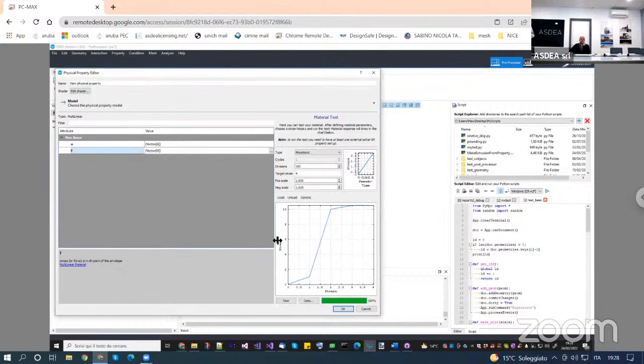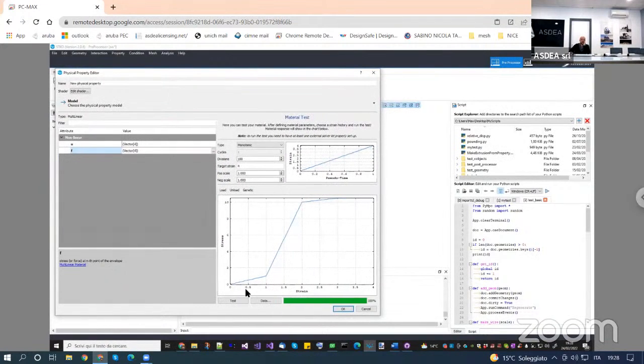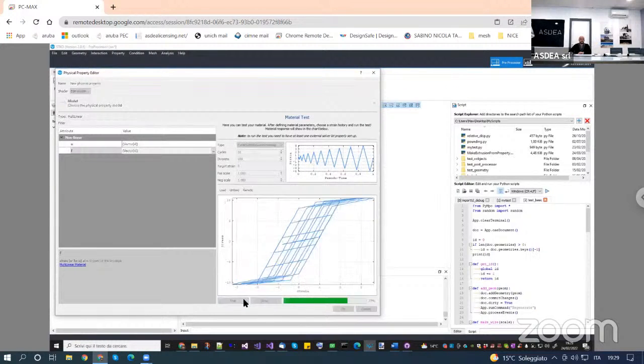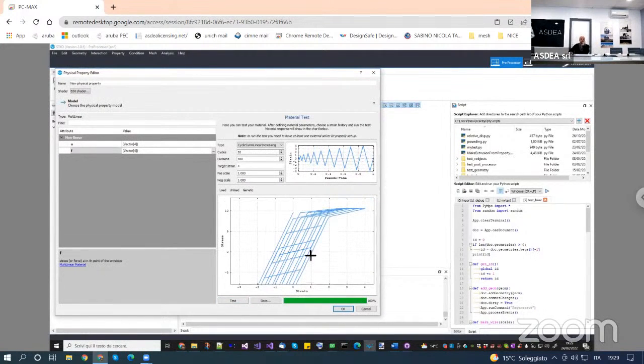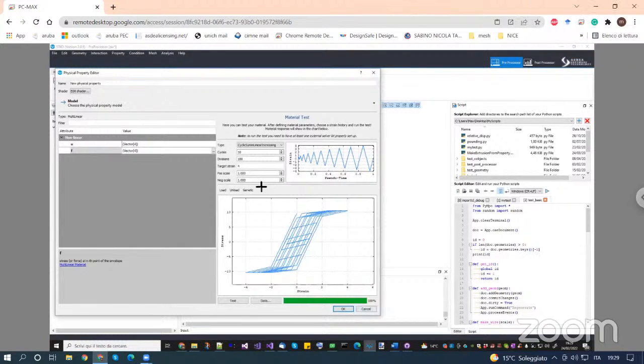Okay, so what I can do here is to create an initial gap, and then it gains stiffness. But if I do a linear increasing, let's do 10 steps, 100, and it slowly reaches 4. Let's do a test. You see, it's not what you want because it goes back with the same stiffness. It doesn't go back with the initial one. So this is not what you want.